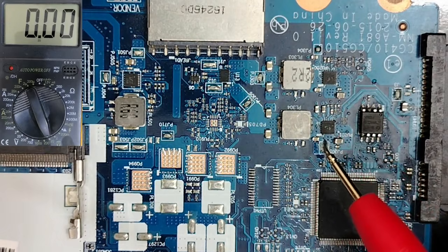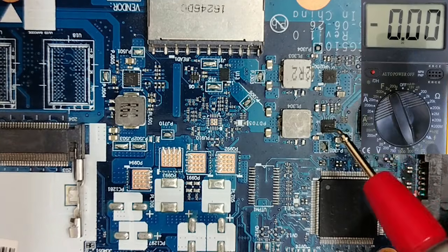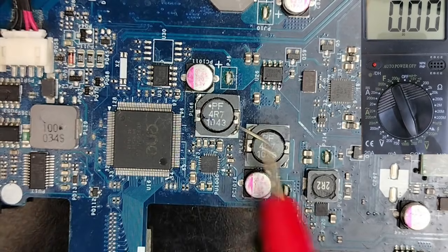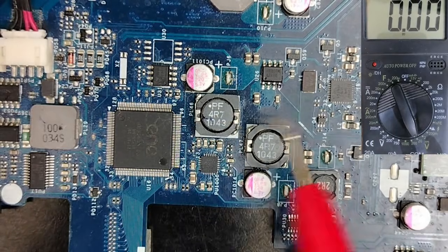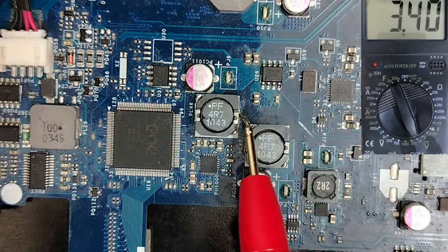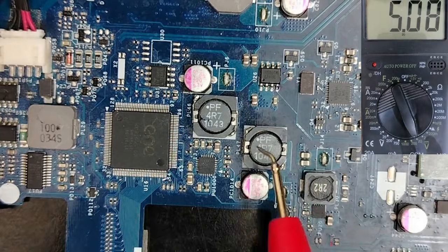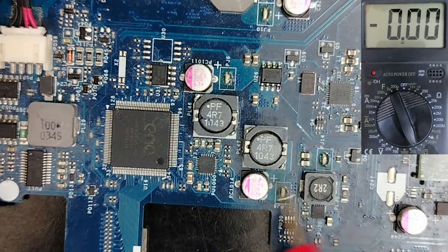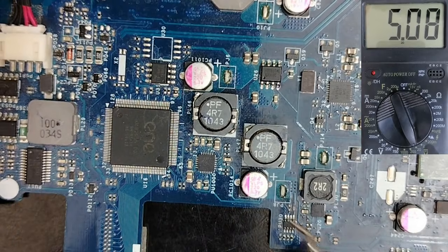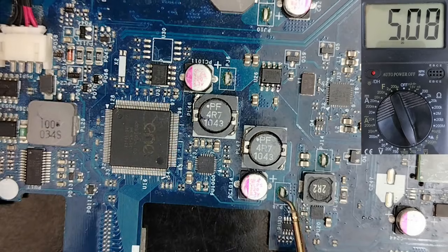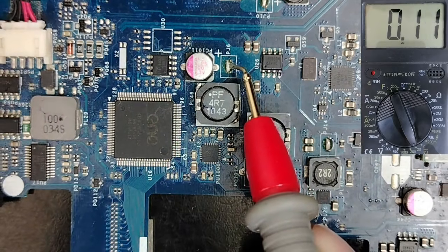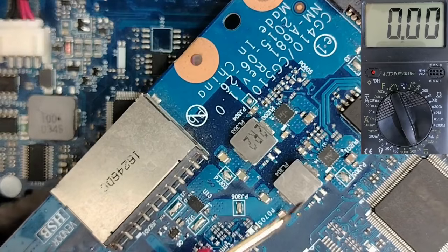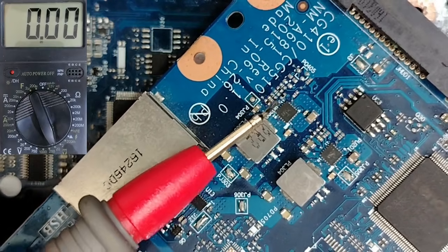But sometimes, guys, you can find MOSFETs instead of ICs like those. So guys, we have another motherboard here. Do you see? We have 2 inductors, duplicated inductors, the same rule. If we check this inductor, for example, we have 3.3 volt here. On this inductor, we have 5 volt. Of course, we have the electrolytic capacitor for this channel. We can even check here. We have 3.3 volt. This one is also for this channel, we have 5 volt, okay, and we have the pad or the test point here. We have 5 volt for this channel, and we have 3.3 volt for this channel, and we have the control IC over here. So it is the same as the other circuit, okay, but for that circuit we have a controller.